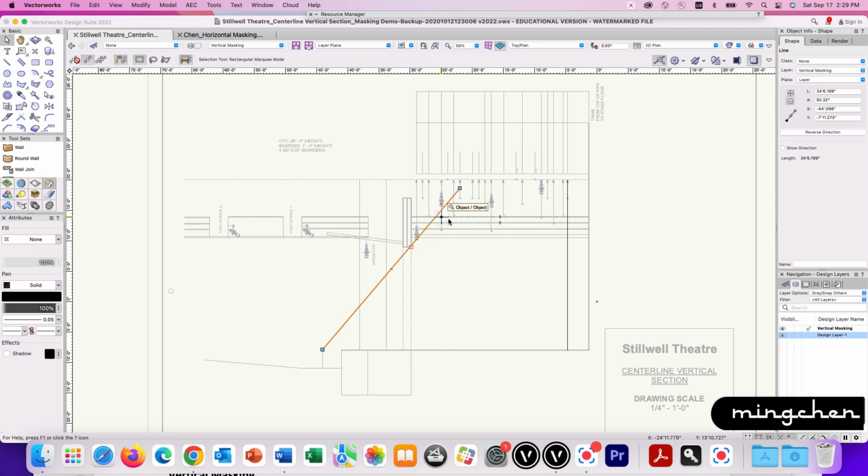However, audiences still can see the offstage space on the right side of the sideline until it meets the top edge of the cyc. Draw a reference line to mark the onstage limit of the borders. Draw a diagonal reference line starting at the critical seats located on the last row of the house. Extend the line through the right corner of the proscenium arch all the way to the cyc and make the second click. This is the line marking onstage side of all the borders.